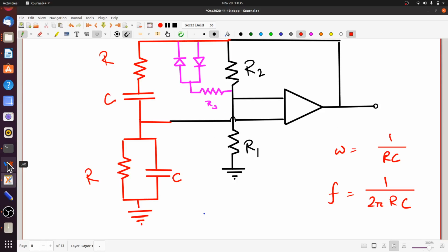The next kind of oscillator that we are going to look at is called a phase shift oscillator. Just to contrast that with this case, notice that here the amplifier part of the Wien bridge oscillator was a non-inverting amplifier that caused no phase shift whatsoever. And the feedback part actually caused different amounts of phase shifts for different frequencies, and hence here the feedback and the frequency selection network are one and the same.